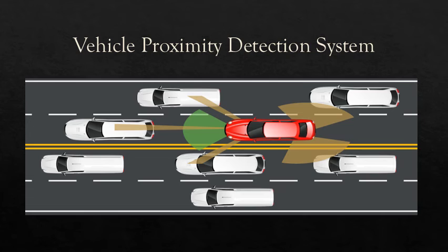Its intended application is to alert a driver to vehicles moving into his rear blind zone, as shown in the figure. A passive ultrasonic system, the HS200 reacts only to those high frequency sounds generated by a moving vehicle, such as road and engine noise.